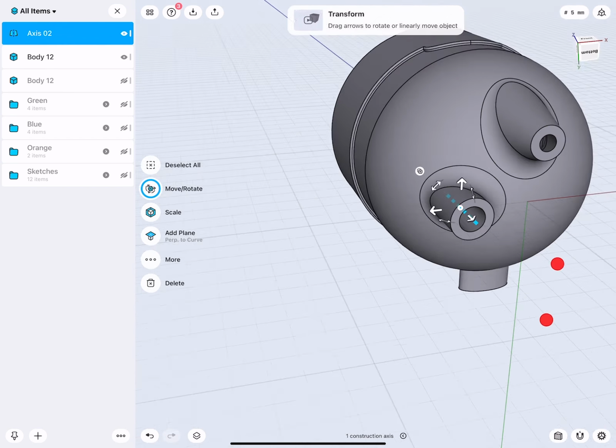How do we now do something that is actually smaller? I need to modify this arm, but I want the shape of the arm to be different, and I don't have to redraw it. So there's also a nice sketch trick. This is the axis line. You see I can dimension it. Here is the endpoint of this line that goes tangent to there. And here I have a line.